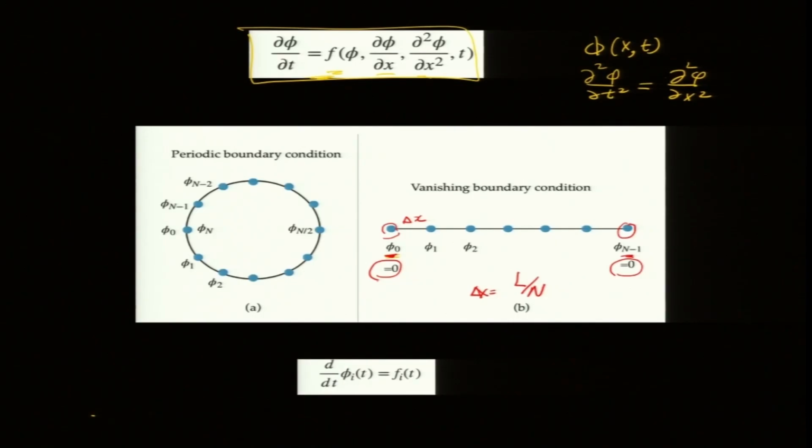So, once you discretize these points, I can solve these phi's not for every point in space, but at those discrete points. So, what happens to this equation? It is a PDE, but now I am going to solve the evolution of this phi at the grid points.